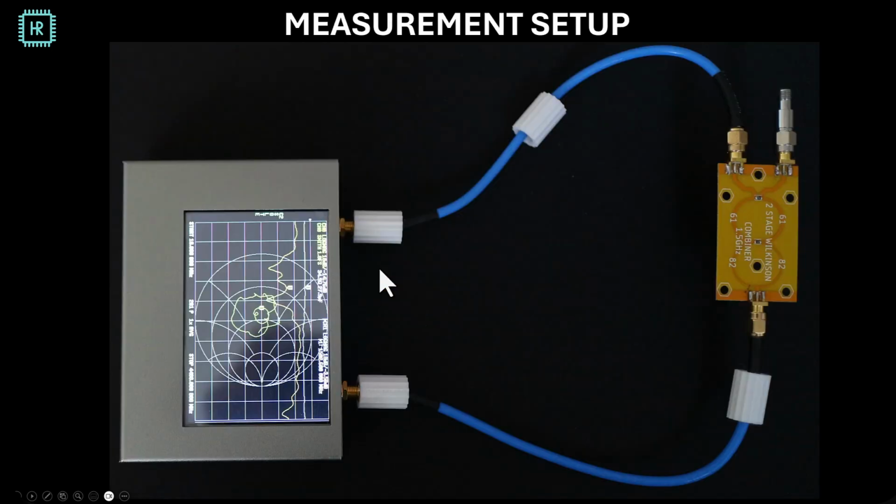It's really easy. So this is the measurement setup I used to measure it. I'm using a NanoVNA. This is the actual board. I'm using a 20 dB attenuator as a 50 ohm load because I found out that the 50 ohm loads I bought, which were very cheap from AliExpress, only operate correctly until 1 gigahertz. So in the beginning I was wondering why this is not working.